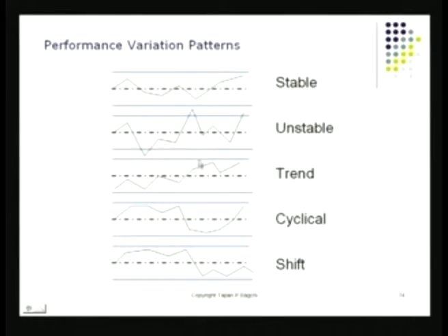The blue lines are the control limits, and look at the way the process is moving. It's slowly rising and rising and rising, and suddenly it will go beyond what is acceptable to us. Or there may be cycles. These may be two guys, one works the day shift, the other works the evening shift, and their settings are different, and therefore they produce this cyclic behavior in the control chart.